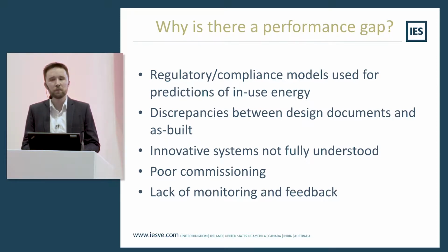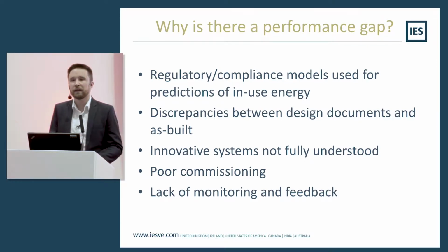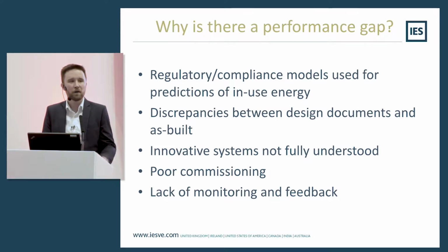As well as that, the performance gap was caused by other issues related to the construction industry, so discrepancies between design documentation and what was actually installed and built, new and innovative systems being poorly understood by designers and installers, poor commissioning or a lack of commissioning, so insufficient budget being allowed for commissioning of the building systems, or insufficient time being allowed when project timescales were squeezed. And finally, there was often a lack of feedback from construction to the designers so that they can learn from mistakes. So maybe a lack of looking at the data from a building in performance and using that to refine the next designs.